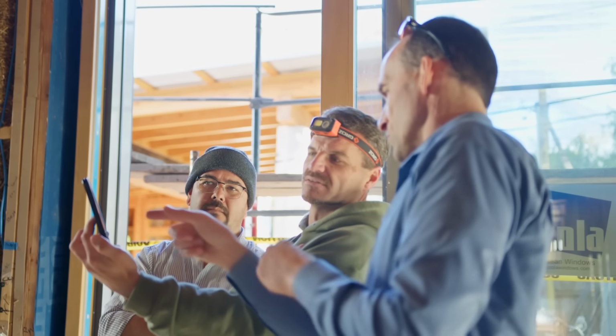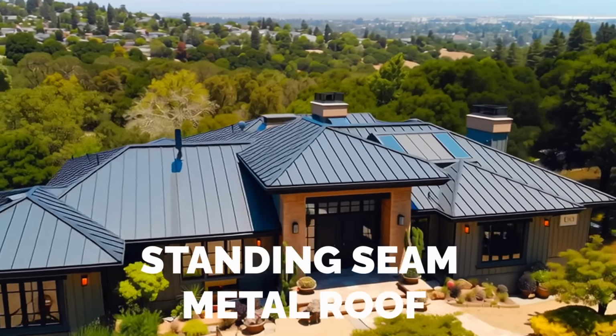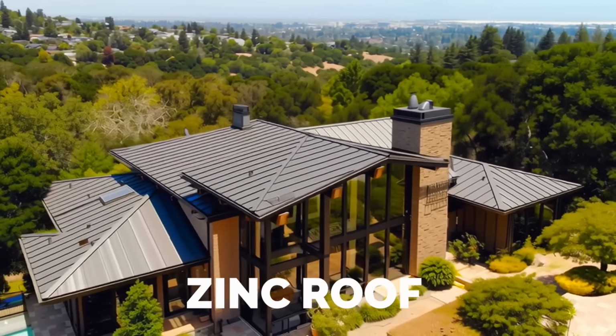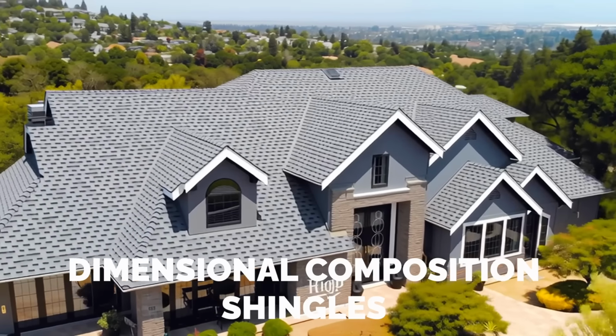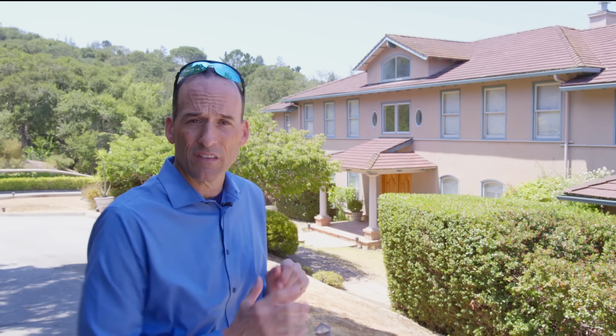Well, the architects came up with a great idea. We don't have to use this heavy tile roof. We can use a lighter roof. Those lighter roofs can include metal roof like standing seam. It can include a zinc roof, which is very, very expensive, just the material itself. We can make a dimensional composition shingle like you see here. So there's lots and lots of options. So what does that mean for this project? Well, that means that if we can use a lighter roof, we're actually taking weight away from the top of the roof, making the house more resilient and more able to withstand earthquakes even with this existing structure.